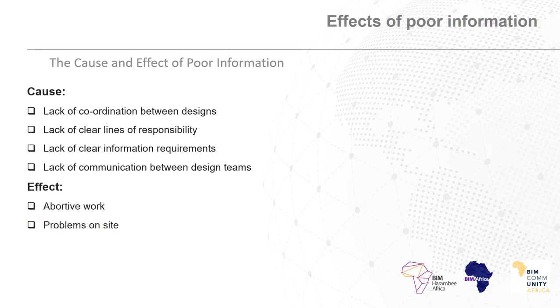You will experience problems on site. If drawings don't align, what happens if you trust one set of drawings and it has an impact on other elements being constructed? Uncoordinated information like this is bound to cause an impact issue. Poor building performance. With longer runs of pipework and awkward junctions, the original design has been compromised and the performance will suffer as a result.